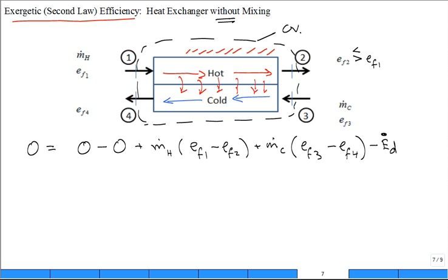And so as it goes through the hot side, here's an easier one, T2 compared to T1. The temperature, what do you think? Did the hot fluid get hotter, or did the hot fluid become warm? It became warm. So the temperature went down. Likewise, the flow exergy went down. So what we do is switch this other m dot h, EF1 minus EF2. Put that onto the left-hand side.